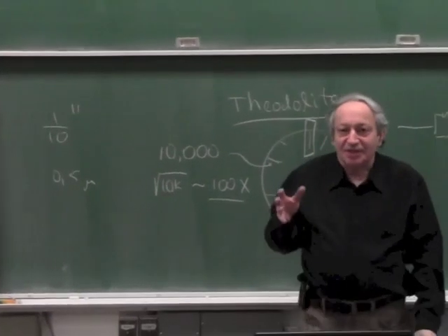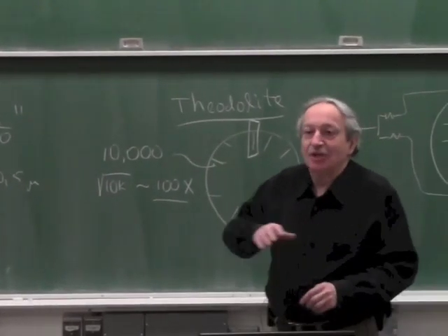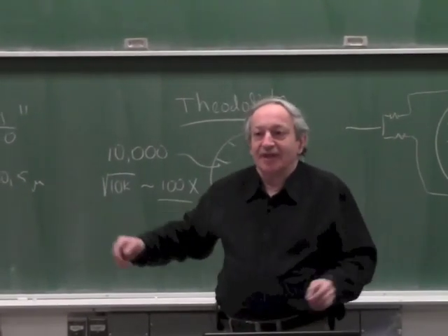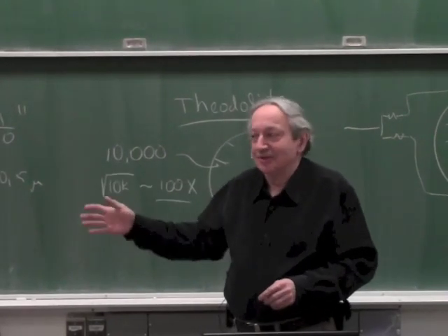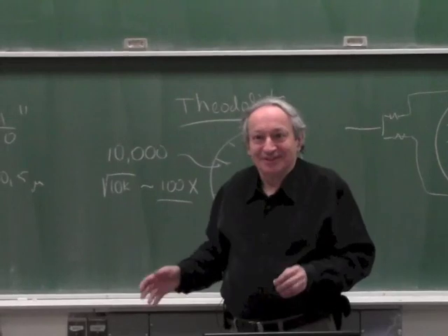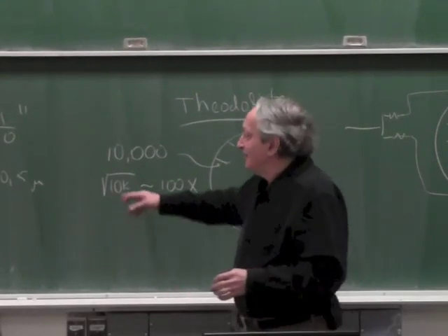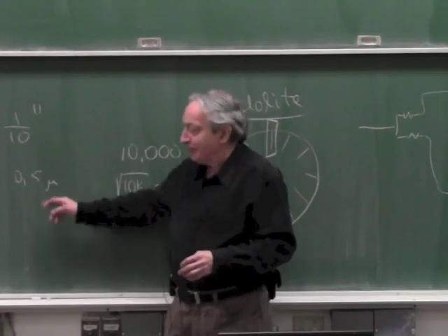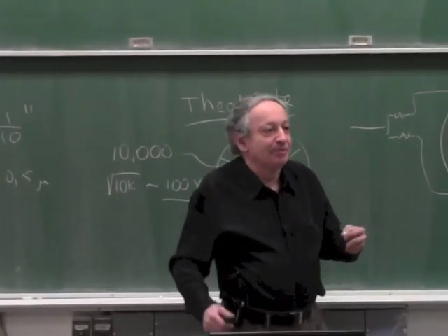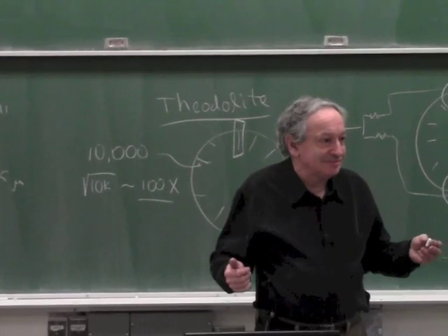It means roughly that if you have a beam 1 kilometer long, and somebody puts a business card under the end of the beam at 1 kilometer, you can detect that it tilted. Just to give you an idea what 1/10 arc-second means. There's a calculation here, because half a microradian is half a millimeter per kilometer.